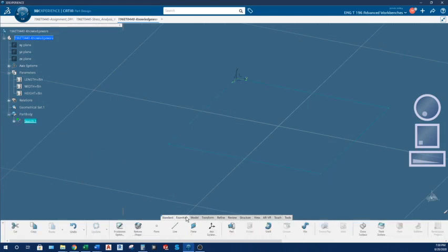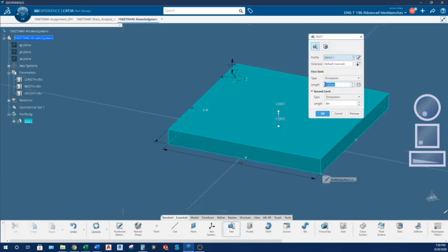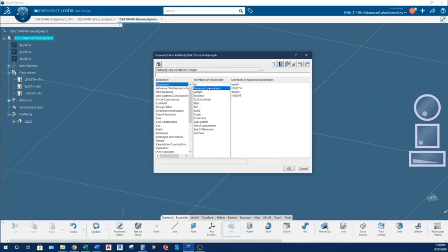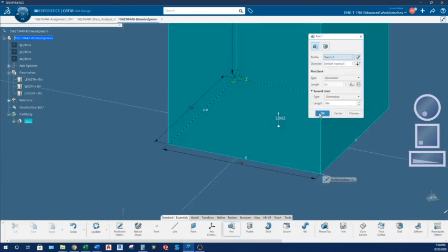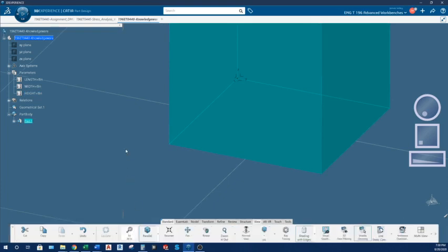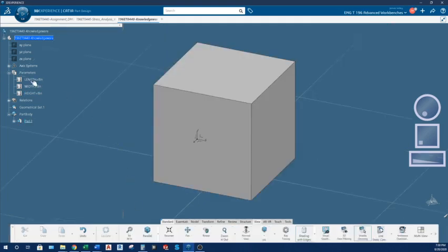Highlight our sketch. Add it. And here, in your link, you right click, edit formula, rename parameters, right, double click. Has to show up here, otherwise it will not be active. Now, to change the size, all we have to do, double click, change it.